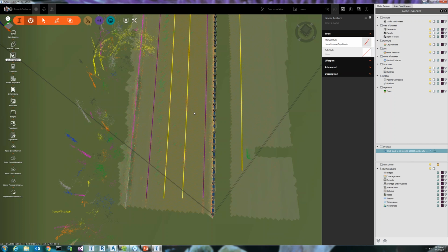Yeah, we kind of went back and forth on that too. Right now we're using intensity values, because in the point cloud world, when I say point cloud, I mean from the laser, the LiDAR world, intensity values tend to be more accurate than RGB, because the camera calibration and everything comes into the picture. So we still maintain that. The one good thing is that when you use the ReCap Pro based tool to process the drone data, it fills in the intensity value from the RGB. I think the other vendors are trying to do the same as well. You can utilize that and it'll do the same job as what I'm showing here. We don't use the RGB at this point in time, just because it might not be accurate. It might give you a wrong answer. That's why we haven't added it yet.